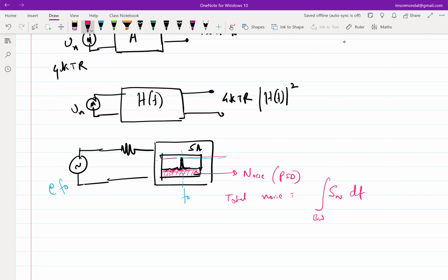Right. So that's what that SAW filter was also doing in our receiver to some extent. But the application was different. The way we introduced the SAW filter was to cut off the blockers, right? The SAW filter also does this job of cutting off out of band noise. So anything that comes out of band also reduces the signal to noise ratio, so it's better to shut them out as soon as possible.